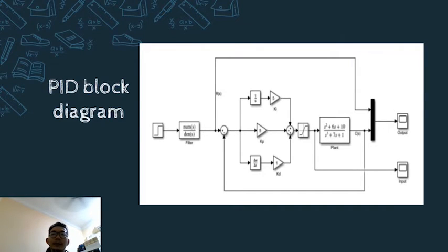A feedback signal from the process plant is compared with a set point or reference signal, and the corresponding error is fed to the PID algorithm. According to the proportional, integral and derivative control calculation in the algorithm, the controller produces a combined response of controller output which is applied to the plant control device.